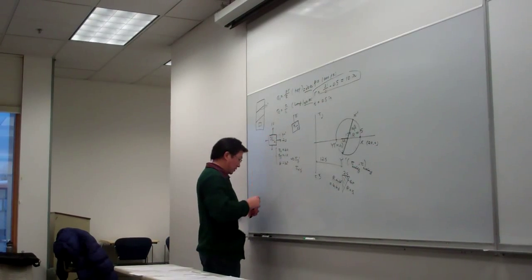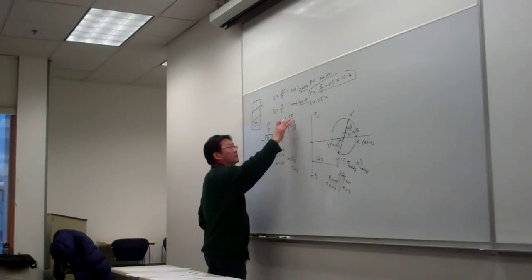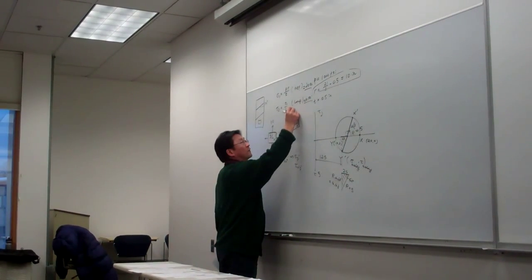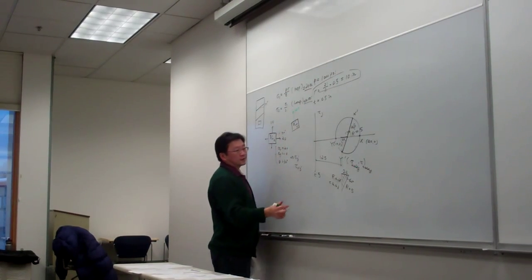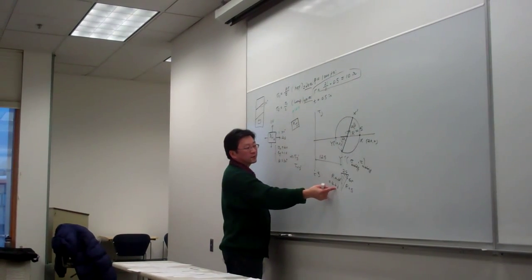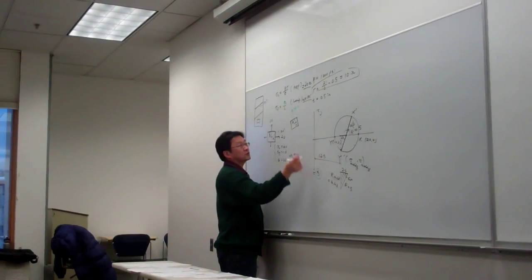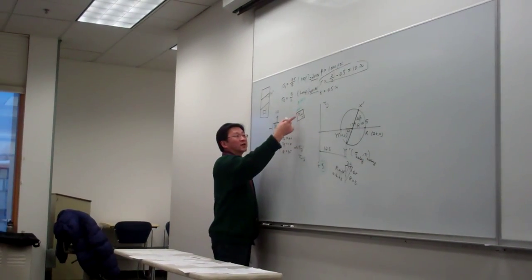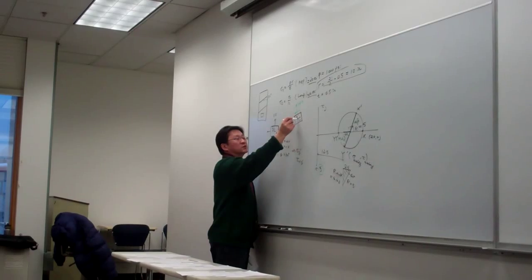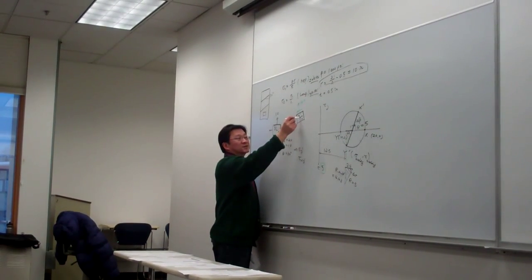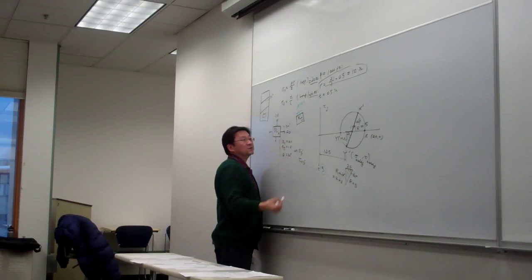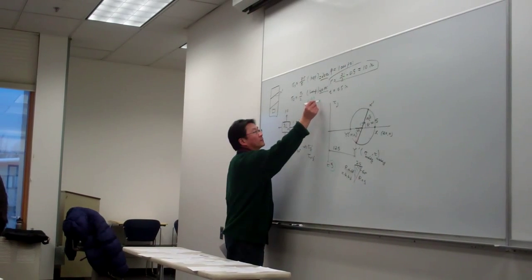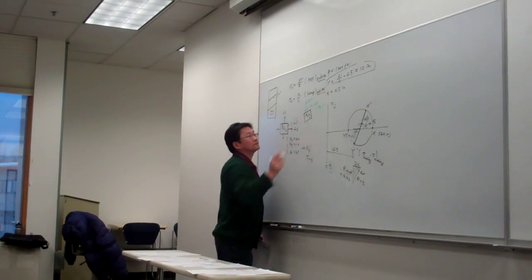Therefore, on the welding surface, we have the normal stress equal to 12.5. And then this one is the shear stress. The shear stress has this orientation. On the Y plane, that shear stress should be pointing in that direction, because that has a tendency to rotate the stress element about the center in this sense. Okay, so this is 4.43, and both units are ksi.